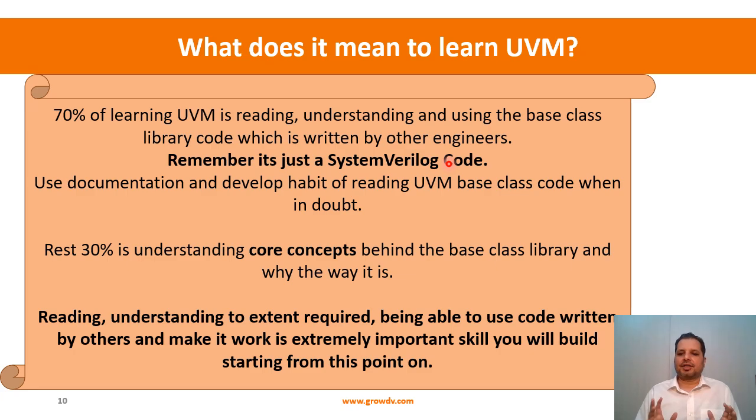So you need to read the documentation, and develop the habit of reading the UVM base class when in doubt, because sometimes only reading the documentation may not make it very clear. So don't be afraid to get into the base class that you intend to use and look at it a little bit. You don't need to get into the full depths of it, but if a few things are not very clear, don't be afraid to look at it, because it's just SystemVerilog code.